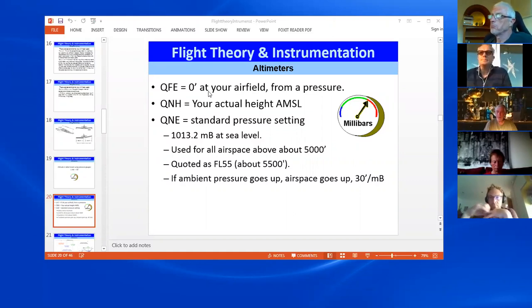A lot of altimeters will actually give you the option of displaying both. It is only relevant, obviously, to where you take off from. This is why it may or may not be that relevant. If you set it to 0 at the top of the dike, it tells you how high you are above the dike. It doesn't tell you how high you are above the landing field.